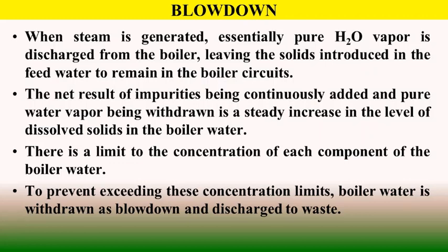Obviously, it is apparent that substantial heat energy is lost with this blowdown, and it is a major factor to detract from the thermal efficiency of the boiler. So we always want to run the system in the most efficient condition, and therefore blowdown is always attempted to be minimized.